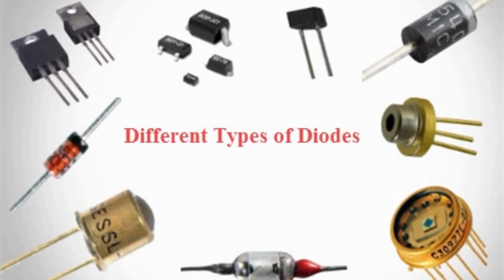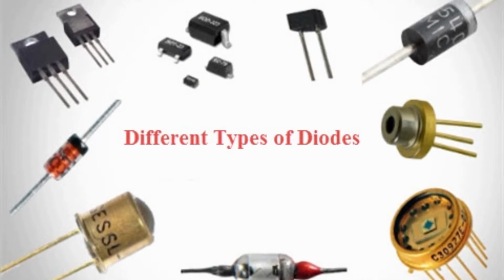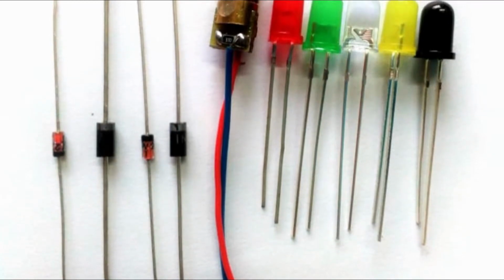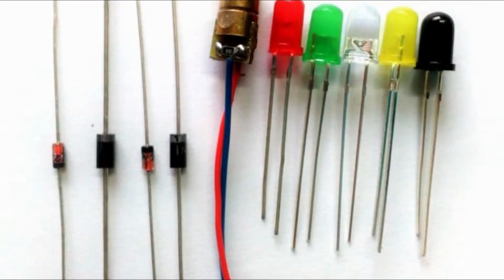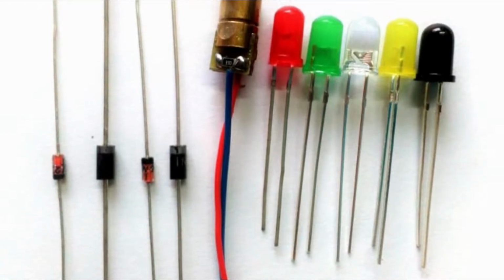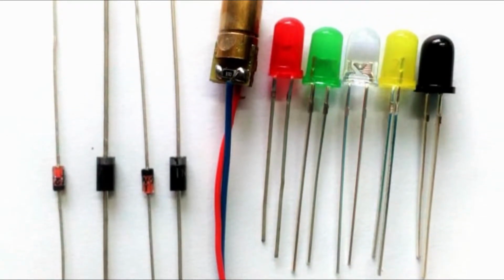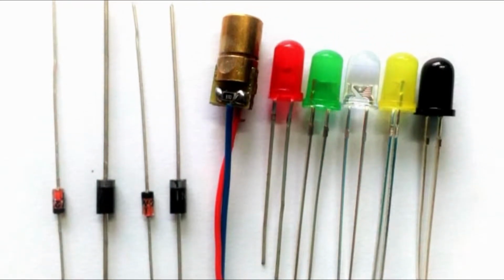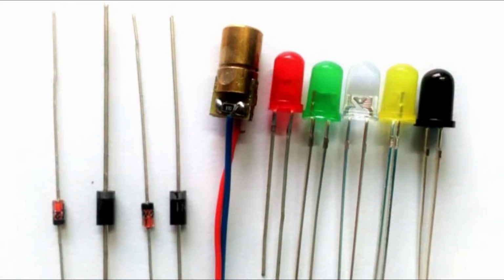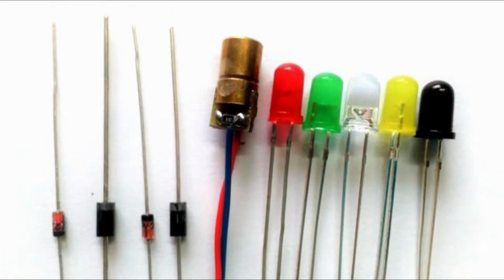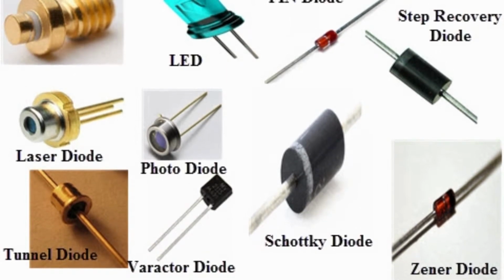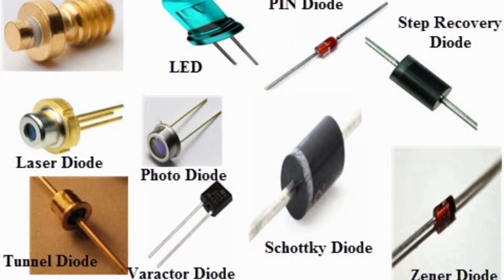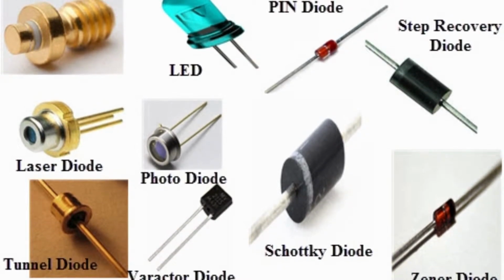A simple PN junction diode is fabricated by doping P and N type layers on a silicon or germanium wafer. The germanium and silicon materials are preferred for diode fabrication because they are available in high purity. Slight doping, like 1 atom per 10 million atoms of the desired impurity, can change the conductivity to a considerable level. The properties of these materials change on applying heat and light, and hence it is important in the development of heat and light sensitive devices.